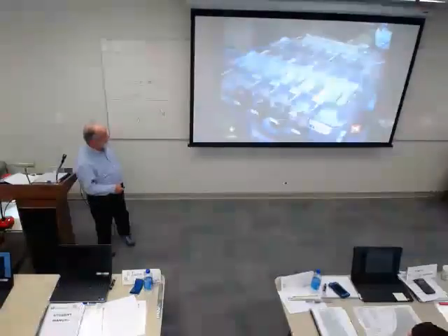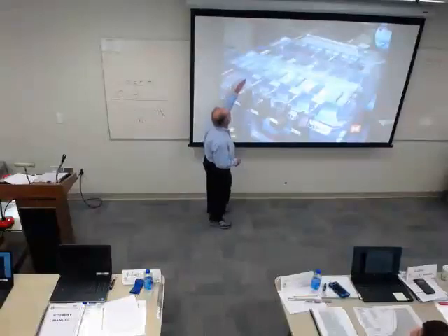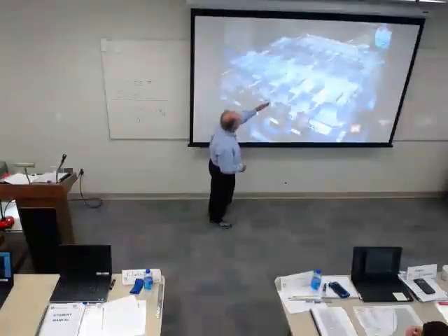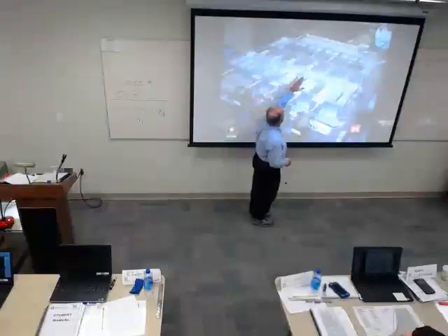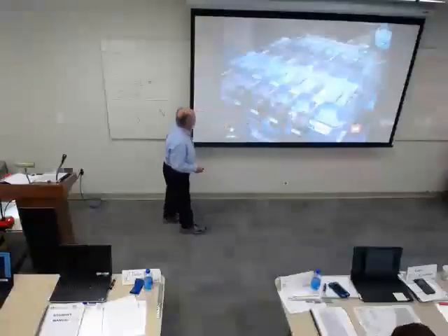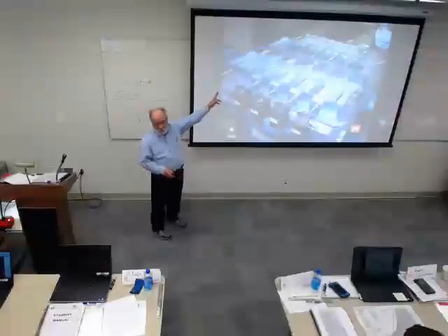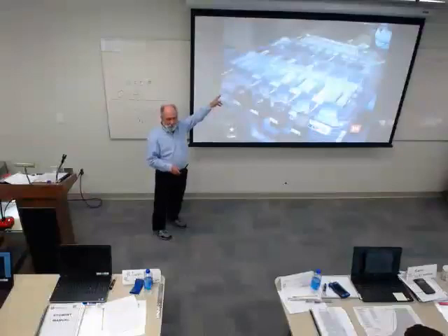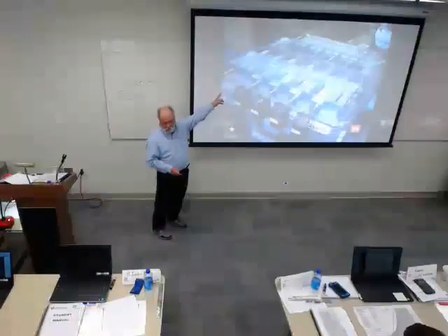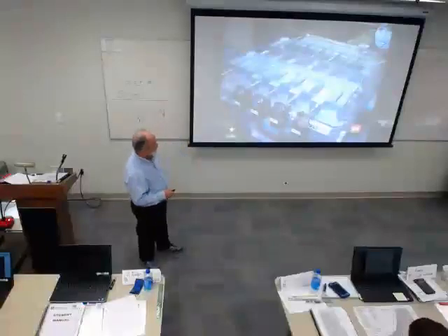Here's what it looks like physically. The ducts are coming off this way. And so here's the one deck, and we have the hot deck and cold deck. When that one's closed, that one's full open. When that one's full closed, this one's full open. They modulate 90 degrees, in opposition to each other.